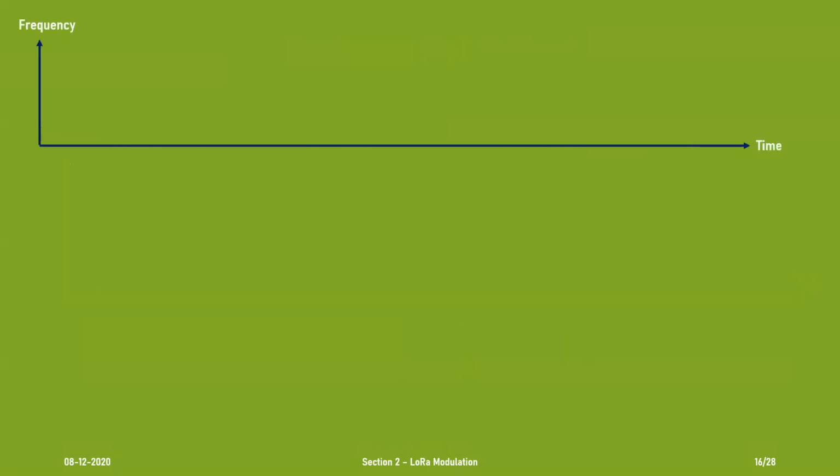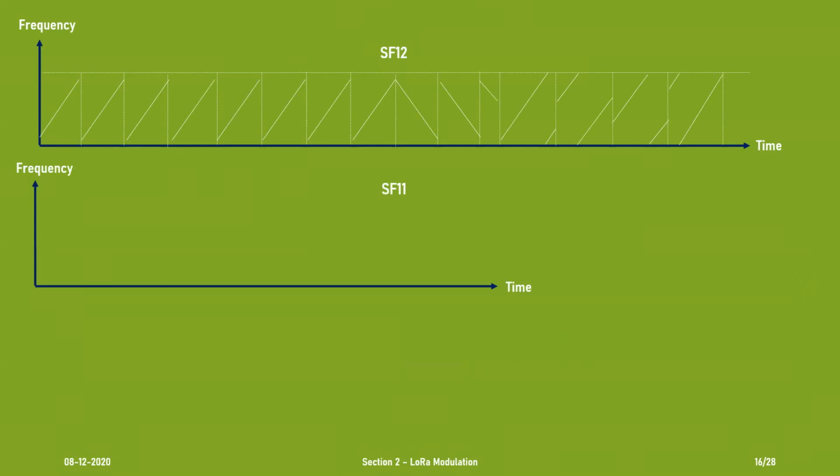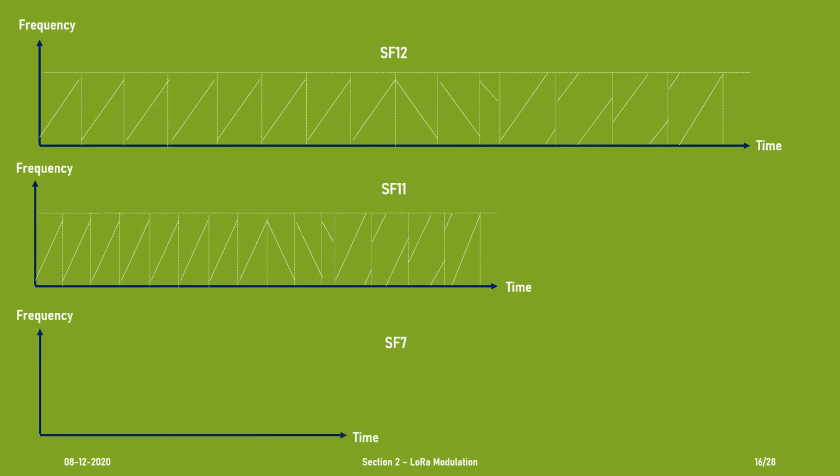Now, in case things that we discussed were a bit complicated for someone who's seeing these things for the first time, just remember that the frequency versus time representation of a spreading factor 12 signal would look like this. It will have some up chirps, then the start of frame delimiter, and then you're having some symbols on chirp. In case of spreading factor 11 symbols, when you're decreasing the spreading factor, all you're doing is taking less time to transmit your symbol because your slope has essentially gotten higher. Your slope essentially increases when you're decreasing the spreading factor, the slope of the chirp I'm talking about.